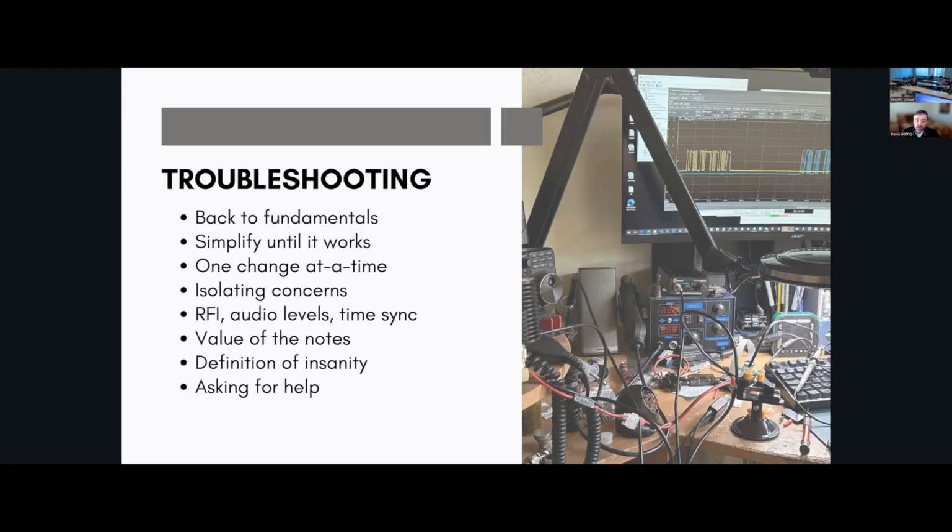A typical situation, for example, is with HTs using an internal antenna, like a rubber duck antenna. These are notorious for not having the counterpoise. You have a radiating element on your HT, and the counterpoise to that antenna is only the metal in the chassis of the radio, and you holding the little ground screw on the side, you become part of the counterpoise. If you're not holding the radio, that part goes away, and the radio and antenna will be looking for anywhere to pull that energy to compensate, to pump into the antenna.